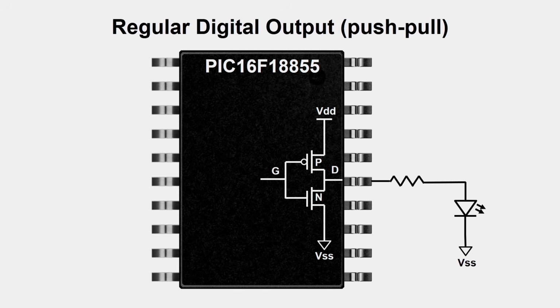I mean, 5 volts is already higher than a lot of other MCUs. And that's written to a port register, and if you set the bit in that port register, you're driving that output pin high. And that's the high, quote unquote, is going to be your VDD plus or minus a little bit of voltage. And that's also detailed in the electrical specs.